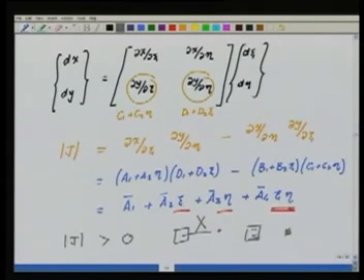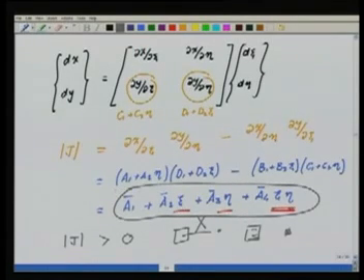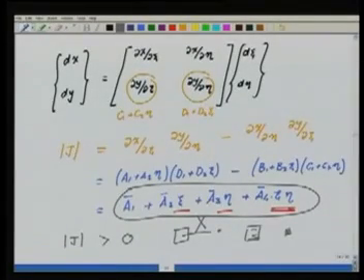When we say the Jacobian is 0, it means the area maps to a point, which we are not allowing; it's unphysical. So we would like to avoid quadrilateral geometries for which this Jacobian can become negative or 0 at a point. Who stops this from happening? Given a1, a2, a3, a4, the four nodal coordinates define a1 bar, a2 bar, a3 bar, a4 bar, and some combinations of psi and eta could make the Jacobian negative at a point.